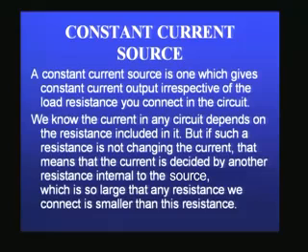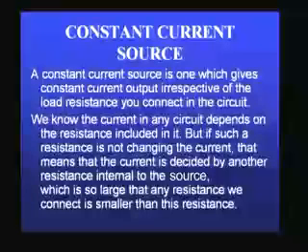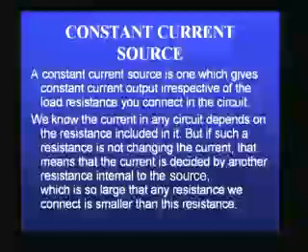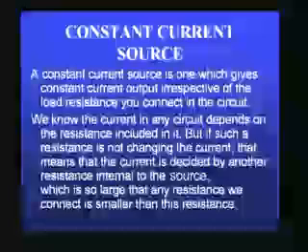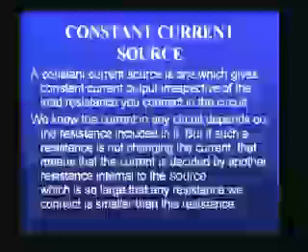Now, when will this current be a constant? When will this current remain constant in spite of the resistance that I connect as RL? You can immediately see that only when I have very large resistance as the internal resistance of the voltage source, you would find the external resistance that I connect cannot alter, because it has been decided already by a very large value of internal resistance, and therefore the external resistance, which is much smaller than the internal resistance, cannot alter considerably the current in the circuit.